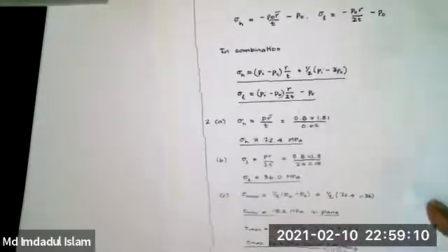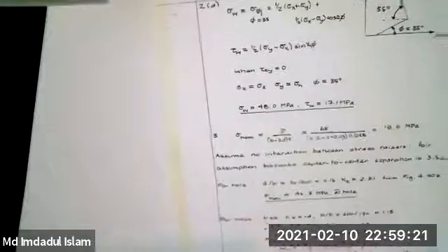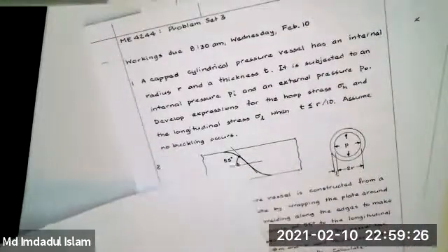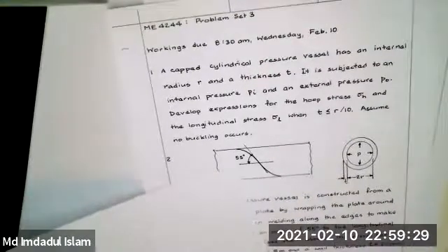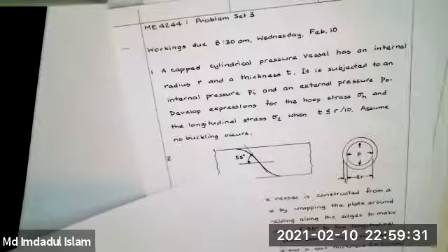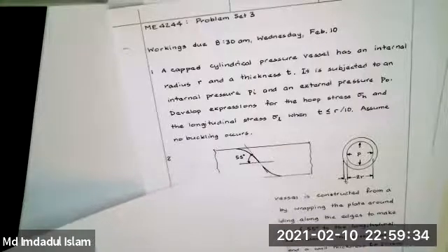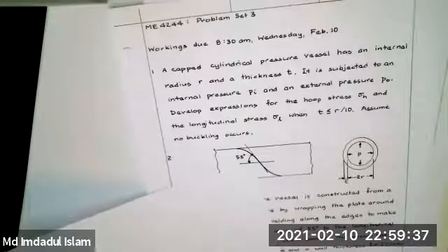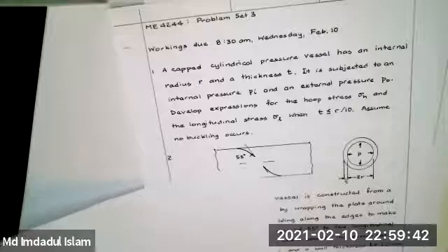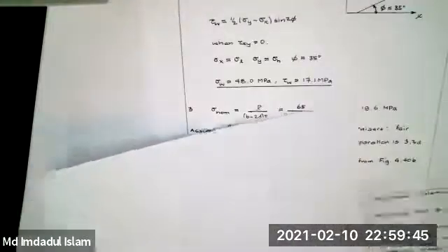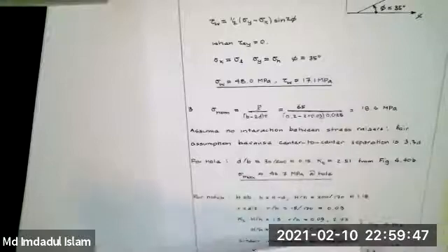Now, oftentimes in the book, some of these sample problems ask you to get the angle where the principal stresses are. Typically, you don't care about this. In this particular problem, you do care. You're going to have a weld, 55 degrees here. This weld will have a certain efficiency where it's well done in the oil and gas industry, probably about 80%. That means it breaks at 20% less than the parent material you're welding together. That weld will separate, and so this becomes a critical thing to look at, in particular what the normal stress is here.